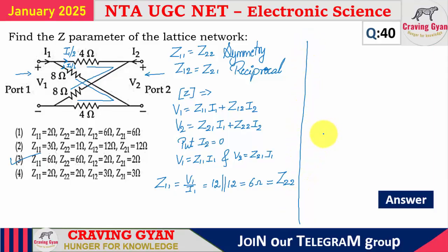Now I want to find the value of Z12 and Z21. Look at the things carefully. The other way is, see directly, we know that it is a lattice network. Z11 is given by ZA plus ZB whole divided by 2. See, this is the value of ZA, and these values are ZB, and this is ZA, right? ZA plus ZB divided by 2. What is Z21? ZB minus ZA divided by 2. That's it. So like this also you can find.